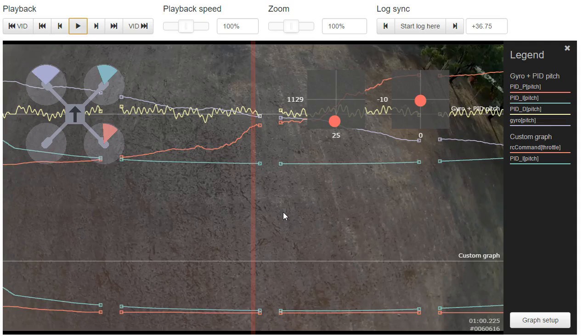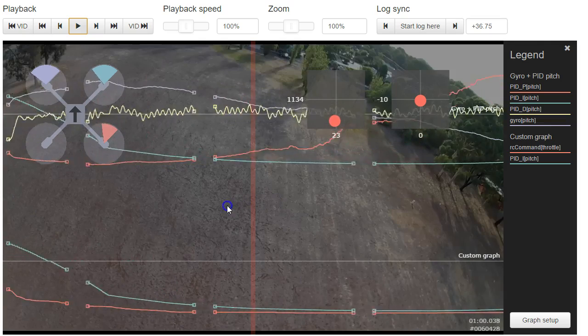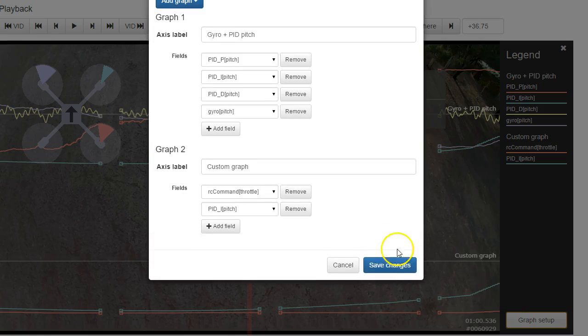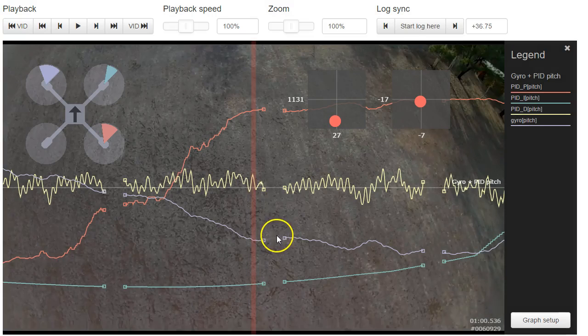So what you've got here is this throttle to pitch coupling, which is just a thing that some copters do, and it's being exacerbated by the fact that your PID gains are kind of out of whack, and they're not right. There's so many times where P and I are opposing each other. A well-tuned copter will have relatively minimal time where P and I are opposing each other.